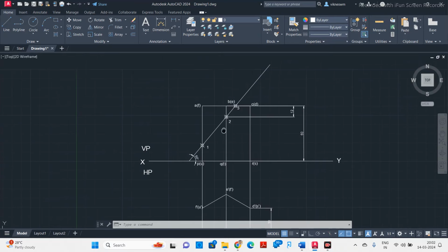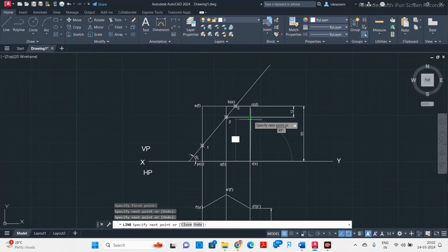So now after cutting this prism along this cutting plane, this top portion gets removed. Okay, so we'll have only this bottom portion. So again you draw a line above this line on this bottom portion so that you can highlight the remaining portion.